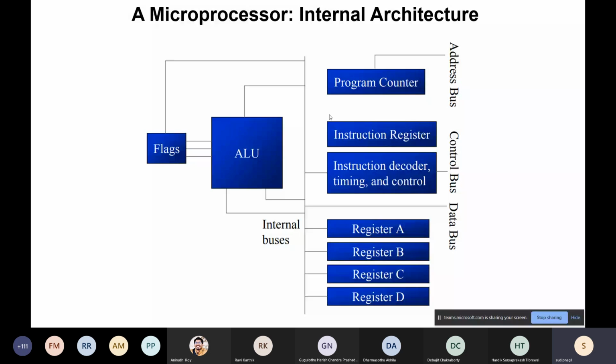After power on, you start an oscillator generating a clock, and then there is a counter: location 1 will do something, location 2 will do something else, location 3 will do something else, and so on. That is called hardware programming for a particular function. So once you start the microprocessor, it will issue the first address, like 0000, on the address bus. Then it will issue a read signal on the control bus, because you don't have any data so far. You have started newly, and whatever data the memory provides will come through the data bus.